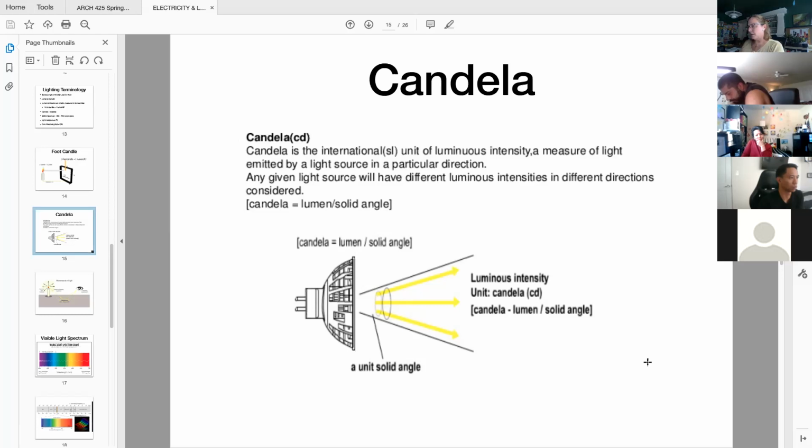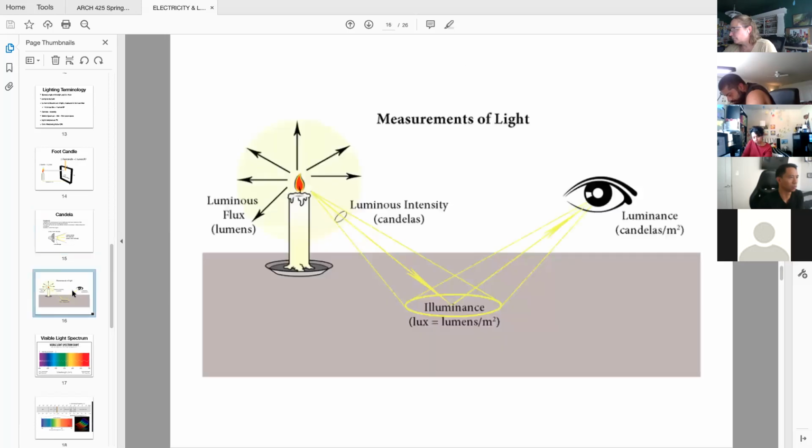The candelas are at the bulb or the lamp for the fixture. And the two of them work together, between the candelas coming out of the fixture and the bulb or the lamp, to help determine what the lumens are going to be on your final surface. Candela is probably the hardest concept to understand about interior lighting.